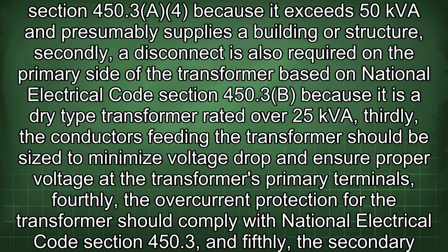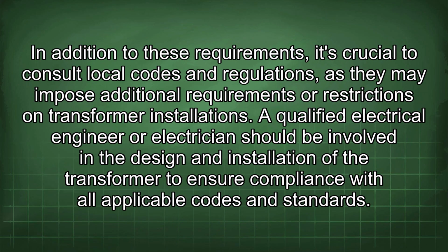And fifthly, the secondary conductors, disconnect, and distribution panel should be rated for the available fault current at the transformer's secondary terminals. In addition to these requirements, it's crucial to consult local codes and regulations, as they may impose additional requirements or restrictions on transformer installations. A qualified electrical engineer or electrician should be involved in the design and installation of the transformer to ensure compliance with all applicable codes and standards.